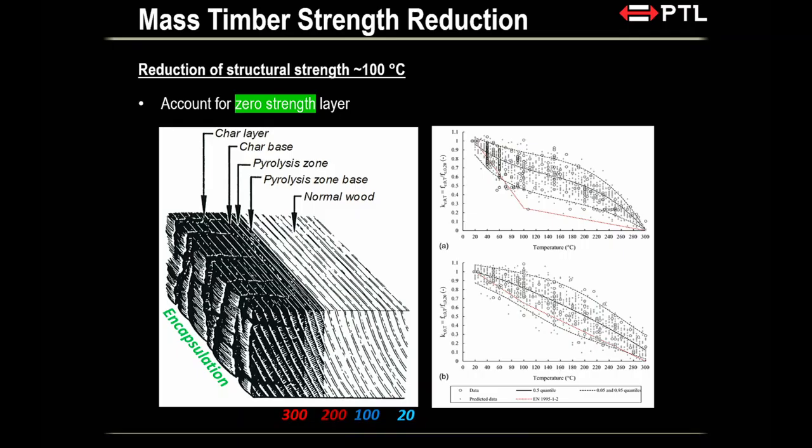No, the thing is, what's happening here is for fire design, I will give you a char depth. You need to add zero strength because the char depth is where the timber completely degrades. If I were to calculate something, I can only calculate char depth. But I don't account for the layer where it starts losing strength a little bit. Not fully, but losing a little bit. That little bit of information is what they call the zero strength layer.